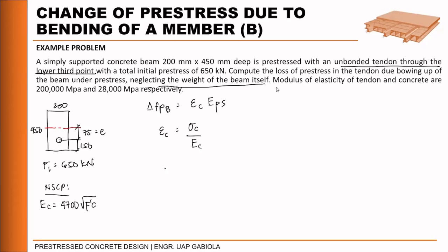So, let's get the stress. The stress will be due to the moment of the member. That moment comes from our pre-stressing because we have a pre-stressing strand. So, in our beam, this is our pre-stressing. Here is our Pi, and then here P is transferred, and it will cause a rotation like this. Okay? So that moment equals P times e. So this will be P times e, that is our moment, times the e we need for the steel, over the I, our inertia.